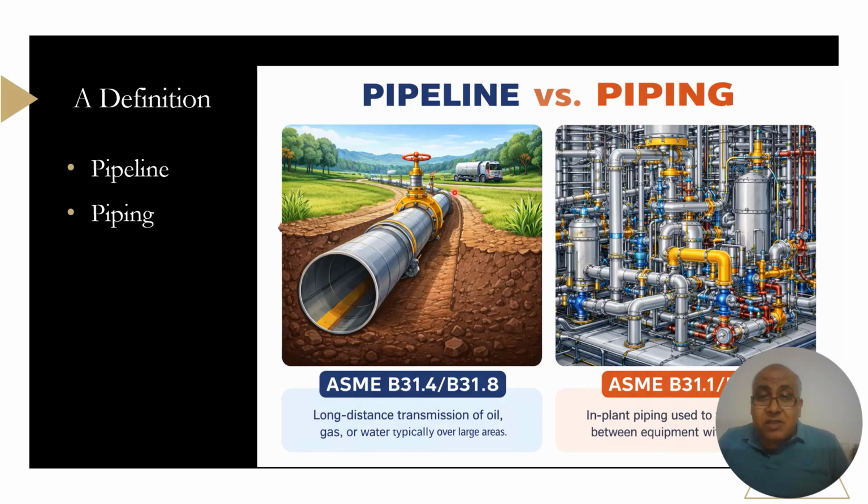We can also present it according to the code and standard. Here it is ASME B31.3, here B31.4 and B31.8. So ASME has codes and standards that differ between the plant and the pipeline. B31.4 and B31.8 are different, and we will discuss them in depth during the course. It depends on an urban location or inside a town, and differs between gas and oil, and in the case of multi-phase fluid or single-phase fluid, just water or oil, or double-phase fluid and so on.